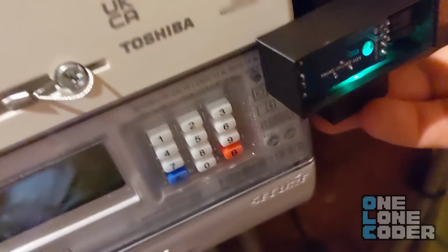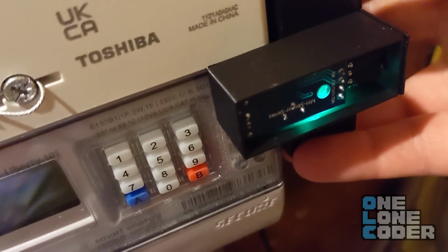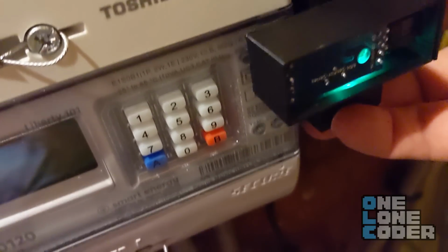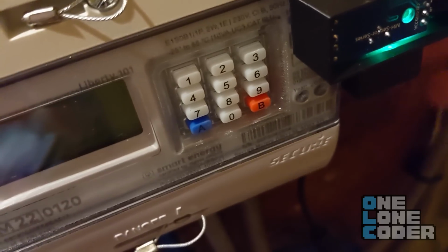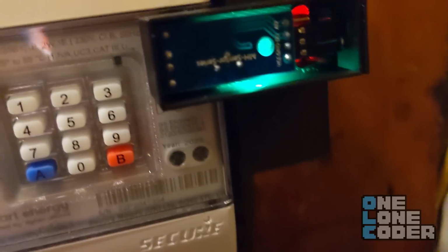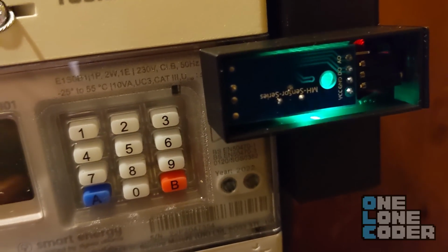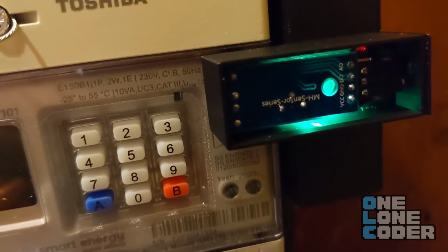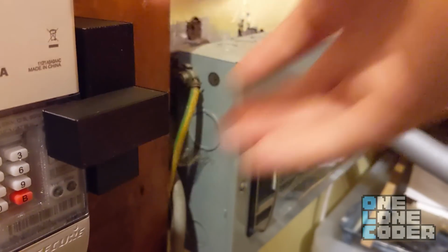To actually stick it to the meter, I've used a semi-adhesive pad on the side. So I can just hopefully get this lined up, make sure that the sensor is over the blinking red LED, and I can verify that that's the case, because now you can see when it blinks red, we also get a green blink on the PCB. I'll now finish the job by putting the cap back on. That'll also stop any ambient light from entering the system. At last the system is installed.